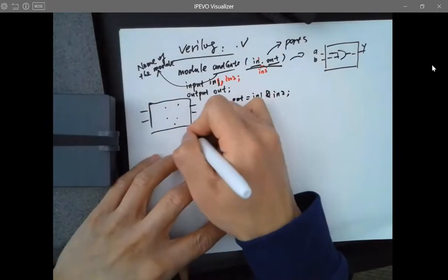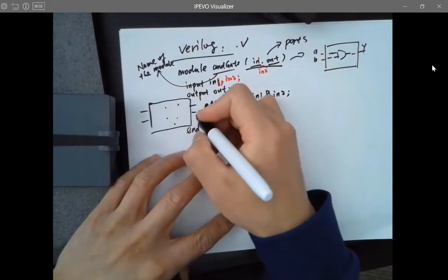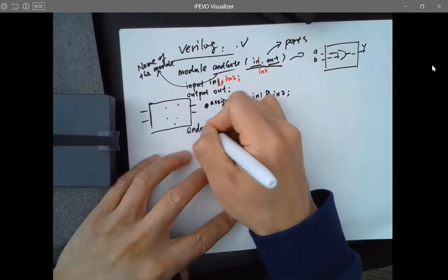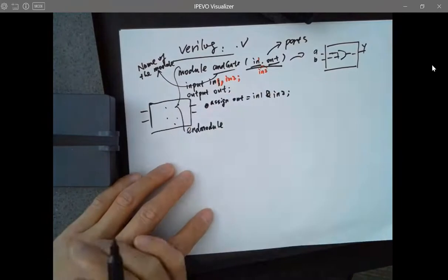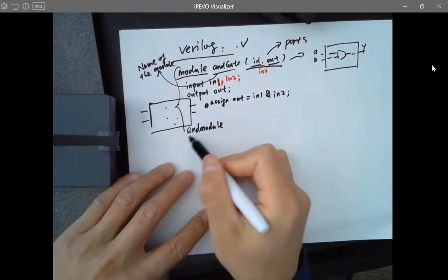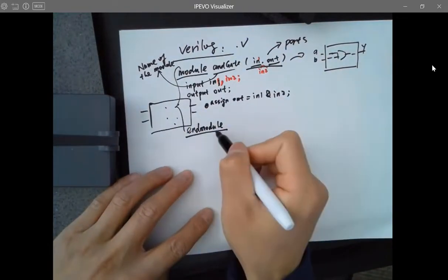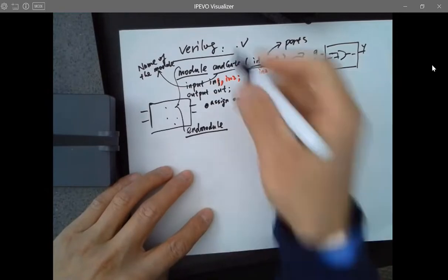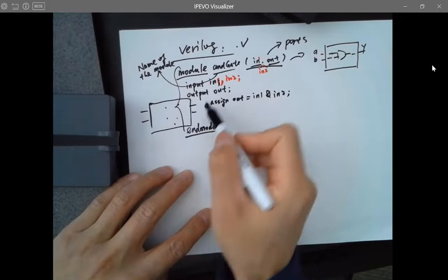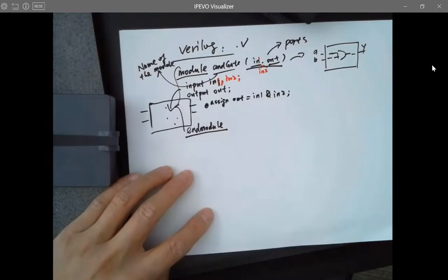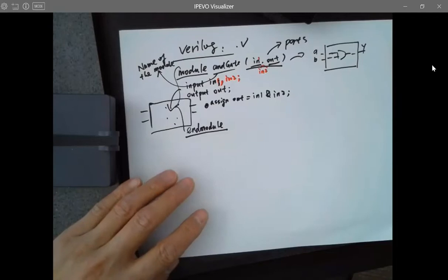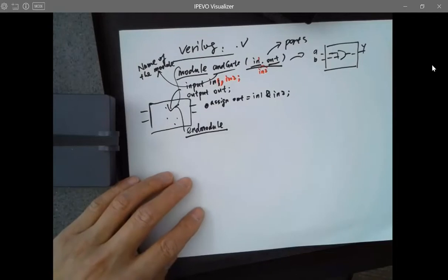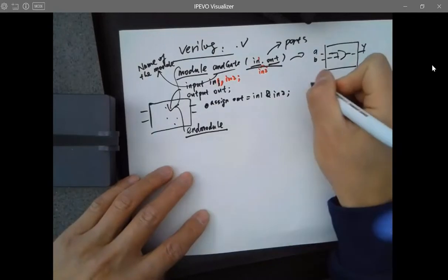That's everything about this module. You need to type endmodule to wrap it up. So it has to start with module and has to end with endmodule. So it knows that everything here is within that device. It's a chip, or it's a logic block.